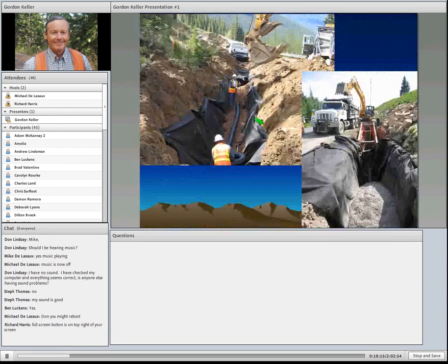Here's a couple forest highway pictures of installations of underdrains. Again, you've got your perforated pipe, your drain rock, and your geotextile filter layer around it. What's happening over here is if trenches get very deep, then there's a safety problem. OSHA doesn't like trenches over 3 or 4 feet deep before you shore them up or support them, so this is actually just a shoring mechanism to keep it safe in the trench. But like I say, these are a moderate investment, so you typically are doing this on a permanent road system.